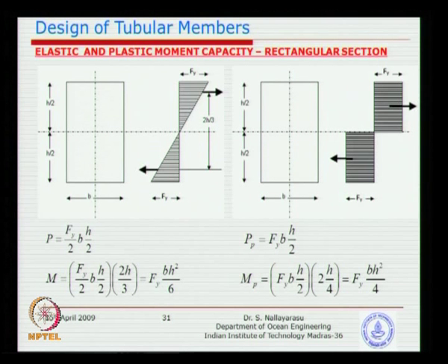This fiber is trying to give the load or the stress to the next fiber, and vice versa, progressively transferring from the external material to inward, because we know very well that the inner material is underutilized. So, we will start transferring the load from the external fiber to the inner fibers. Ultimately the stress distribution becomes uniform like this. When you do the same integration, this is called a sectional redistribution.